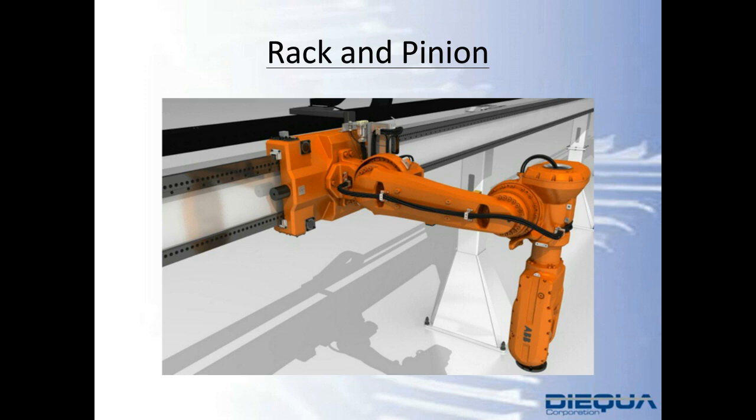In this application, as is typical with most robotic systems, cycloidal reducers are utilized at each degree of freedom or at each joint, lending themselves to the axial, radial, and moment support of the load, as Roberto previously mentioned.